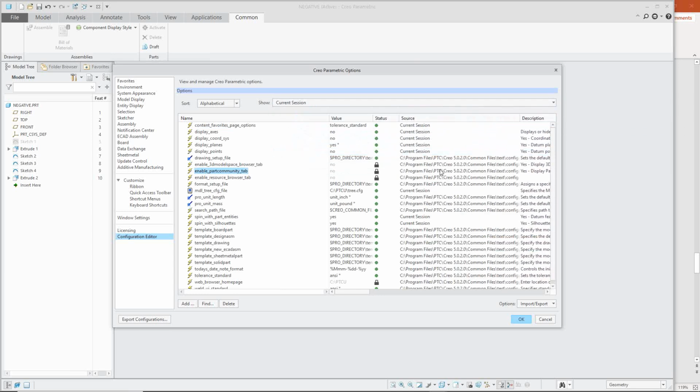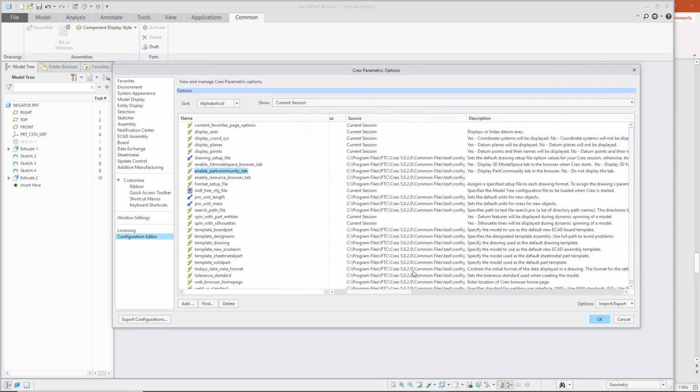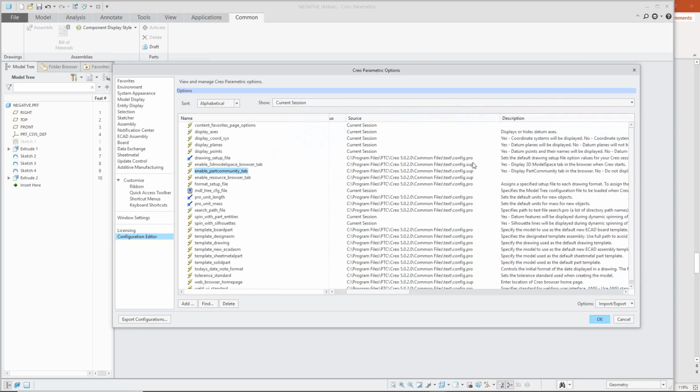So that's where the benefit comes in: we can go in and see which config files are being read from where and what options are inside of each one. So my thing is just simply be mindful. The two places that I write config files to are the common folders, the text directory, and that is your config.pro and your config.sup. Now, I will set settings inside the SUP file that I don't want to be overridden, and the config.pro file that I want to be set generically.